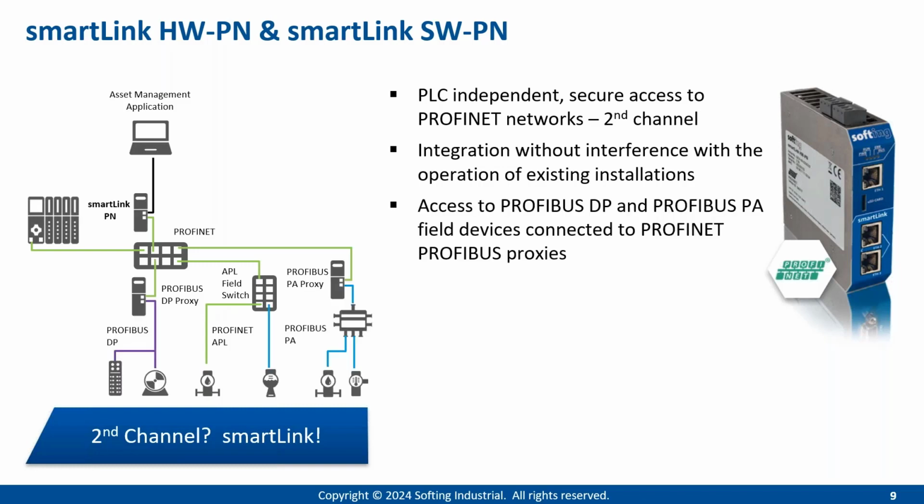Besides Profinet devices, we are also supporting Profibus devices that could be either Profibus DP or Profibus PA. And you see here different scenarios for how we support them. That's typically done by supporting proxies from Profinet to Profibus, which are a standard specified in the Profinet specification.